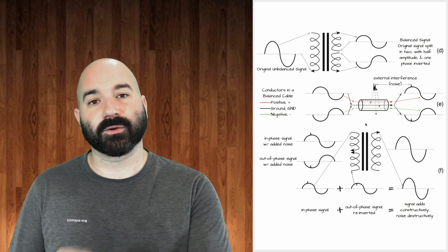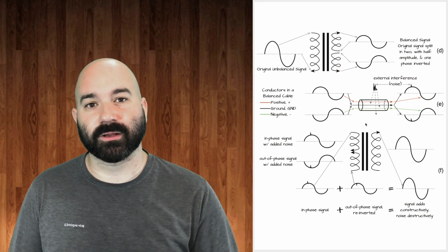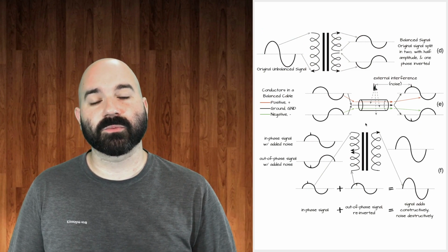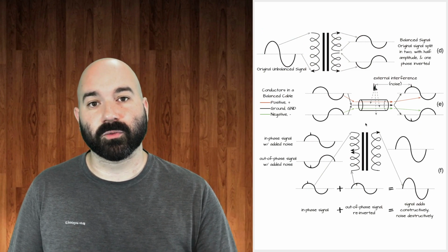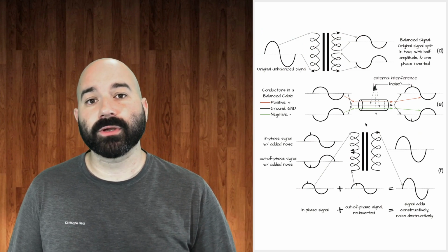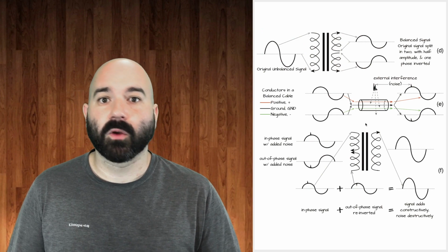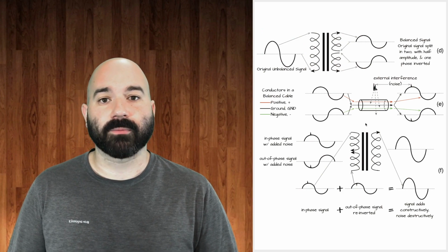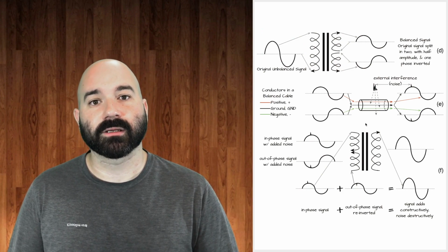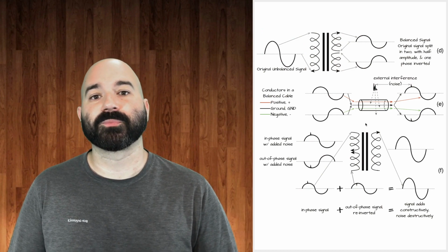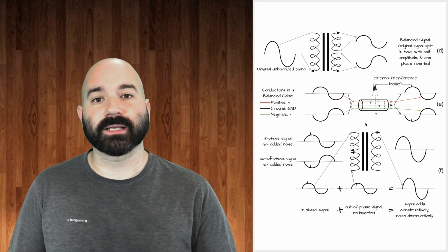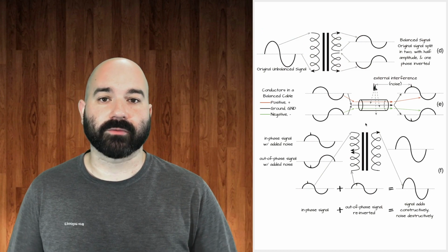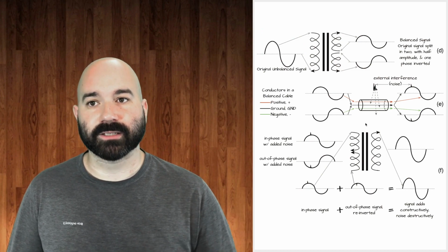What they did is they disconnected the ground from the ground through the electric circuit in their house and their building, so that if a problem does arise, rather than the excess voltage being dissipated and sent to the ground as a safety measure, there is no grounding. That can result in fire or people being shocked. And there are accounts of people being electrocuted and fires happening due to no ground on some devices. So if you do run into a ground loop problem, do everything that you can to find a device that will safely disconnect the grounds between the two devices, but never pull the ground out of a plug that goes into a wall. That is a big hazard.